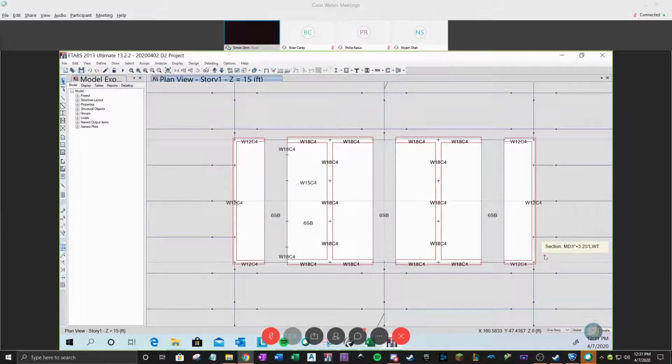For now, one thing, gravity wise, 12 inch is usually okay for one story, but since we're going to design a 40-story building, our wall thickness is much thicker. Just for a heads up, you can see the overall layout of a core wall, most outer wall circling the outside.